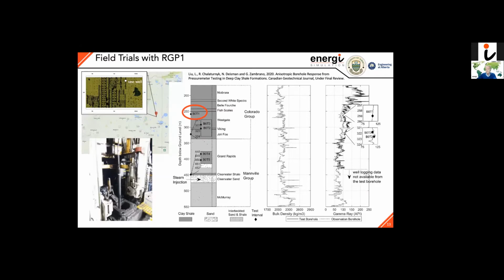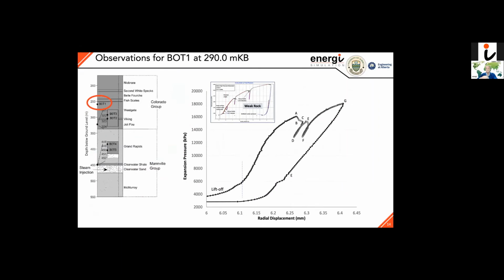In that particular test, we slid the pressuremeter down into a pre-bored hole, set it in place, and then started to actually inflate the pressures. And you can see even here from these images that I showed before, we're already at 14, 16, 18 MPa. And this is the data you get if you take the average data inside the tool. You can generate a curve like you had seen in the cartoons. This is real expansion data for the Westgate.